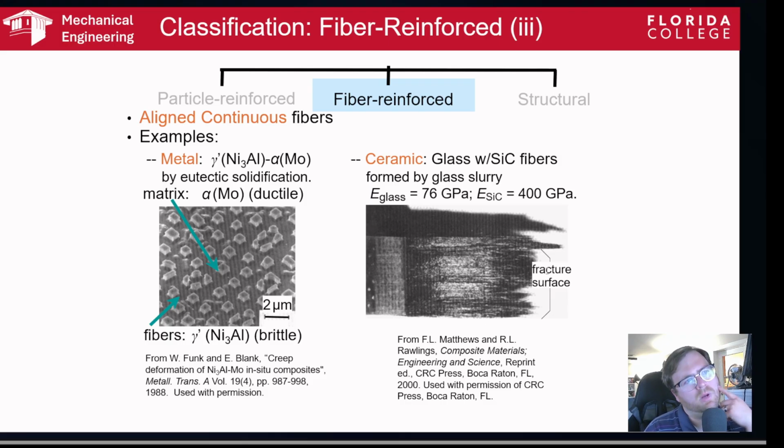And you can actually see where it broke here, which is very interesting. Here we see an example of what's called fiber pullout. If you see fibers being pulled out of the material, it means that it did not bond well to the surrounding matrix material. So when composites break, if you have fiber pullout, it means that your interface, the contact strength between the matrix material and the fiber material, was not very good.